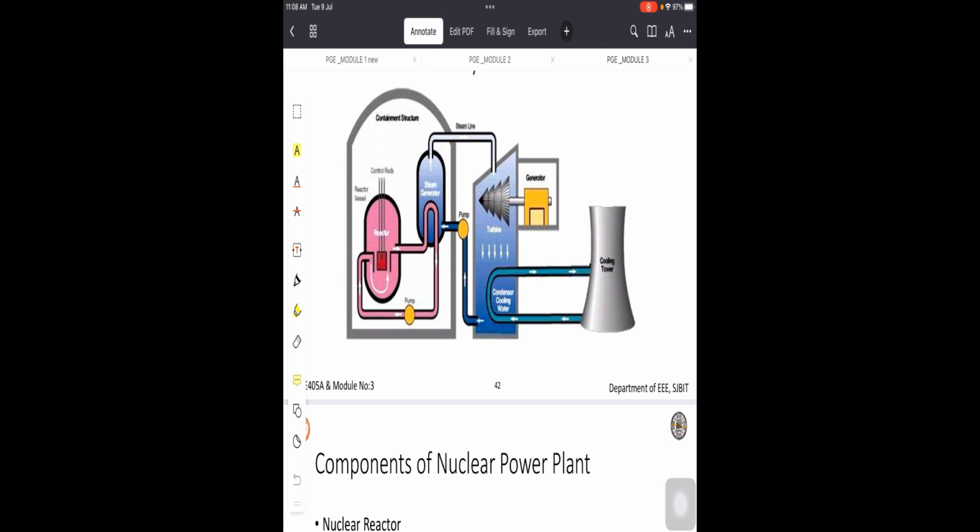The next important component is the moderator. The role of the moderator is to control or moderate the reactor core and reduce the neutron speeds to a value that increases the probability of fission occurring. So here the control process is taken care of with the help of a moderator. For that purpose we use graphite, heavy water or beryllium as the moderators for the natural uranium control process.